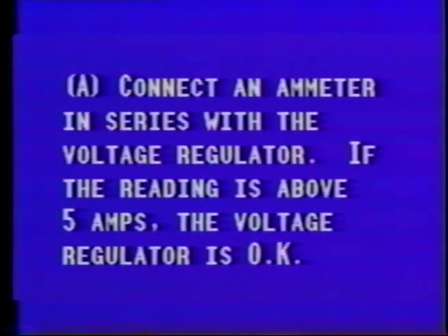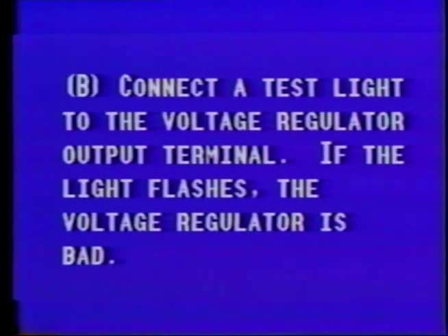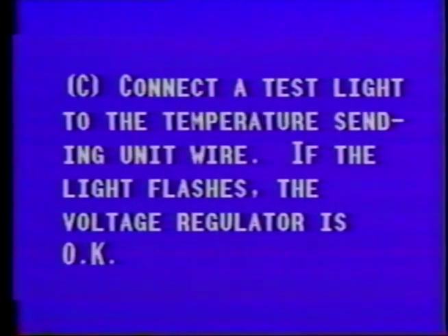In the simple choice question, we see in response A, the technician is measuring amperage, not voltage, so this response can be eliminated. Response D is incorrect in that the meter setup described would be meaningless, as you are not measuring anything except perhaps continuity of the sending unit to the engine block. Response B describes the expected reaction, but the wrong interpretation of these results. So, the correct answer is response C.